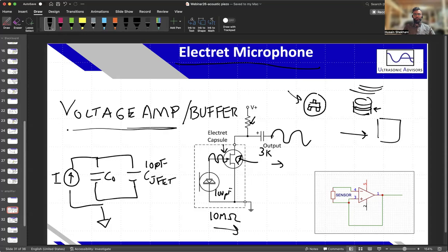Weaker sources of noise may compete with the signal of our transducer, or the charge that's being generated by our transducer. It no longer has to compete because you put an amplifier here. So it allows you to attach other components. Like now you can attach whatever filter you like, or whatever you like to do here, without worrying about what it's going to do to your transducer. So you effectively separated. You made your sensor a black box basically at this point, in the sense that you no longer have to worry about your transducer voltage or transducer capacitance as much, although it's still important because in this case it'll still have some impact.